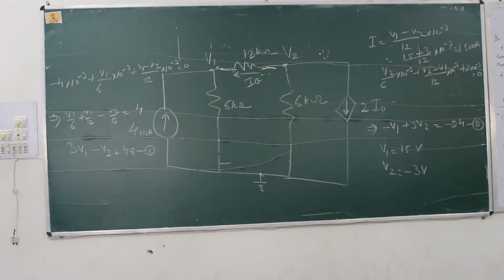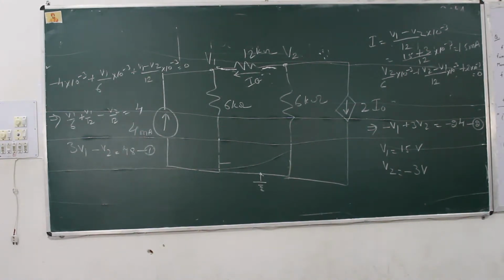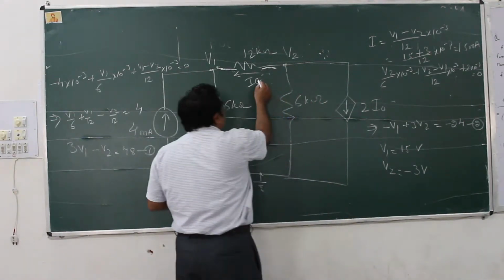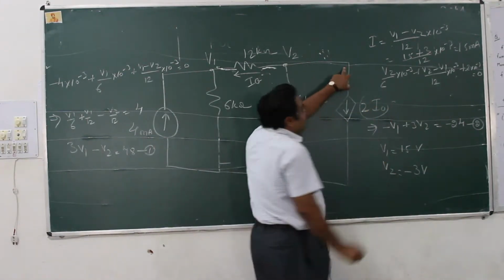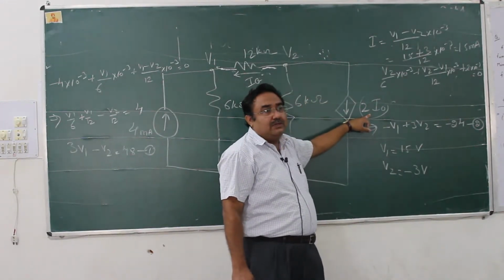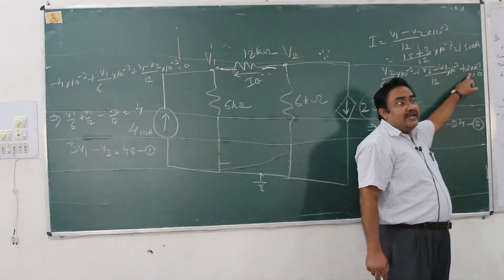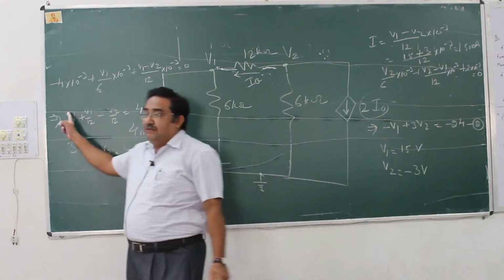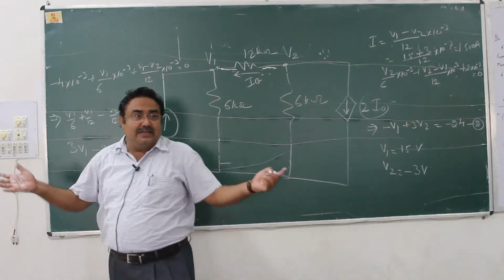Is it clear? Now, after you write down all the equations at each node, this all remains the same. Now, after writing all the equations, there will come this term also. For example, in writing this equation here, instead of 2 milliampere, now it will come plus twice I naught. Is it clear? But my real unknowns are which ones? V1 and V2. This is creating a problem.